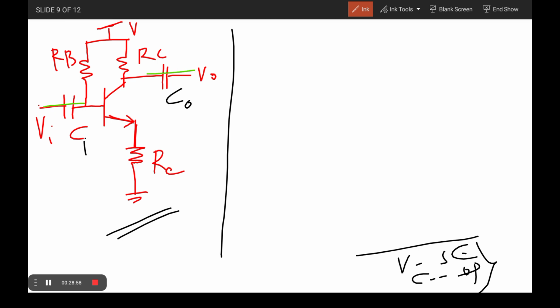You have to represent it individually. Therefore, it is a voltage source, and this can be represented individually. It is nothing but RB connected to ground. This part is generally called the input. Internally, it is a small re. This base emitter represents a p-n junction nature. Therefore, internally it represents some resistance, and that resistance is generally called small re.